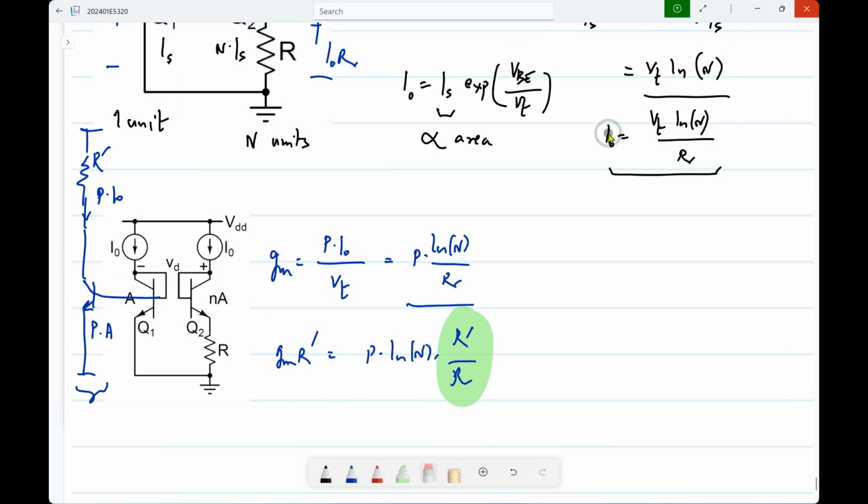Okay. Now this you do many times. In this case, it works out exactly. We know that GM is inversely proportional to absolute temperature. You have current directly proportional to absolute temperature, they cancel out and you get constant GM. In many cases, you will observe some variation with temperature, and maybe if it is also sensitive to bias current, you can have some other variation of the bias current with temperature and try to get the entire result to be more or less constant with temperature.